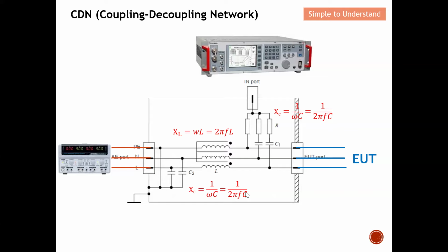So they multiply by C, the capacitor. Typically, C is a very, very small number, so this product will be a very, very small number. When we do the impedance, which is 1 over a very small number, you can imagine it will become a very, very big impedance, because the frequency is small, just 50 hertz, and C is typically like 10 micro, let's say. When we do 1 divided by a very, very small number, the impedance becomes a very, very big number. So the power supply will not want to move down this path.